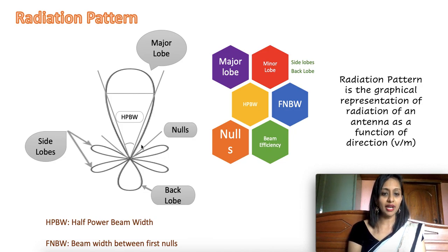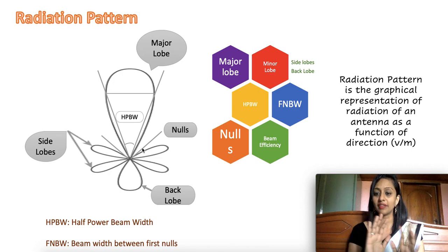Assume I have a receiver exactly here wherein the radiation pattern is not reaching. Though the receiver is very near to the transmitter, my radiation is not covering that area. Hence I will not have any information there, or my power thrown is not received by this person. Those points are called nulls.